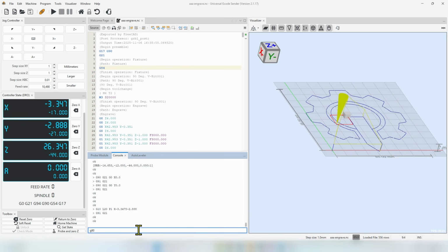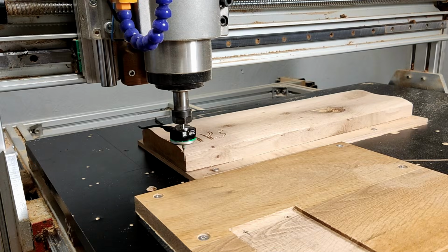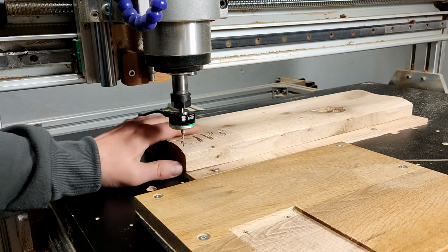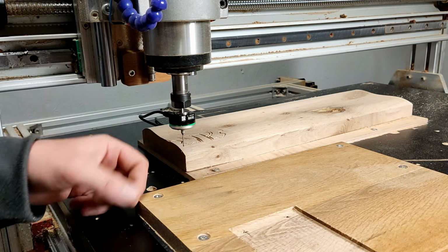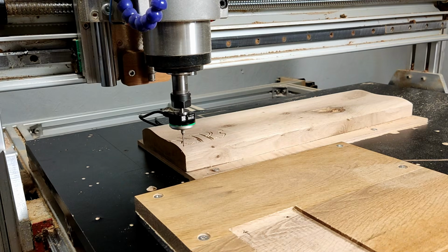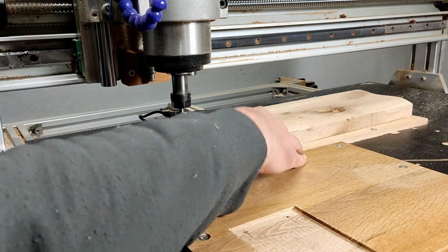Let's switch to the G90 mode. Now the machine really is in G90 mode as it is written here in the DRO. Now I can raise the Z and I will do something because I've already engraved this part and I don't want it to interfere with the probe. I will move the X for 10 millimeters and I will tell the machine that here is X0, so it will start from here on.